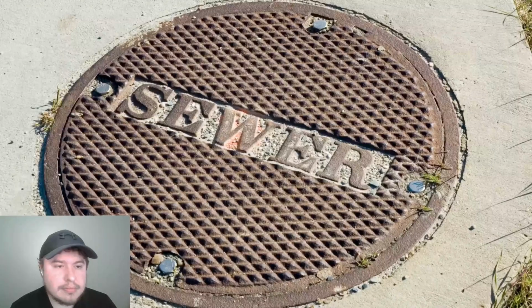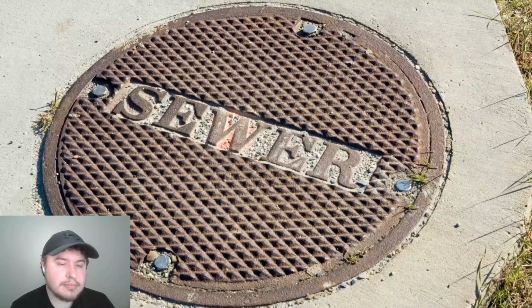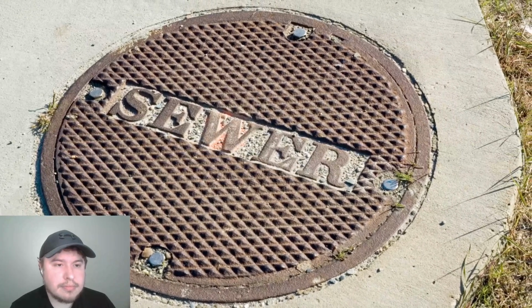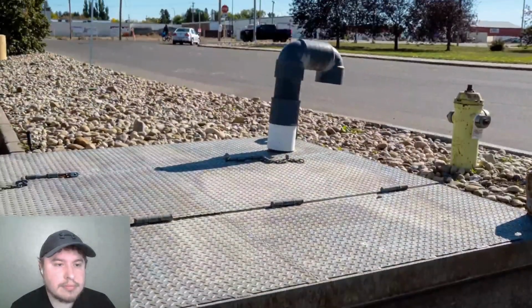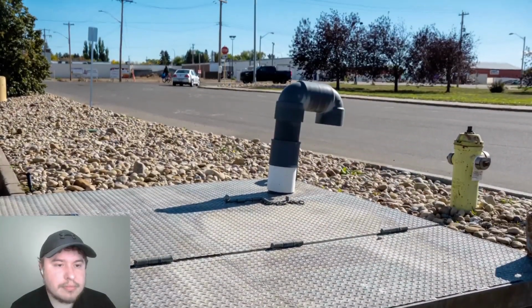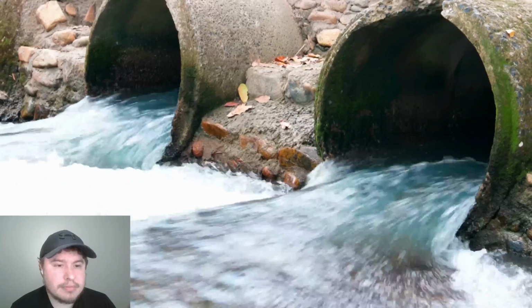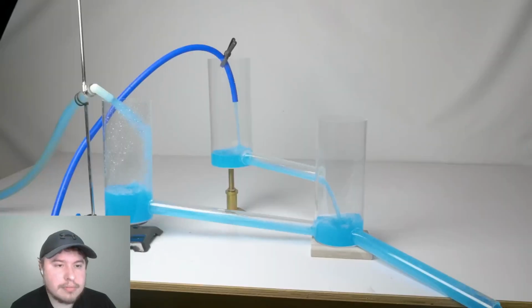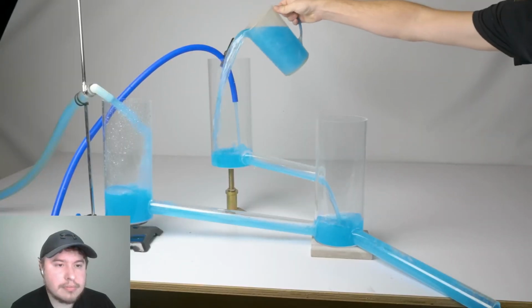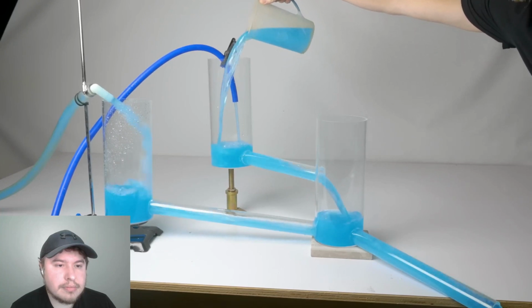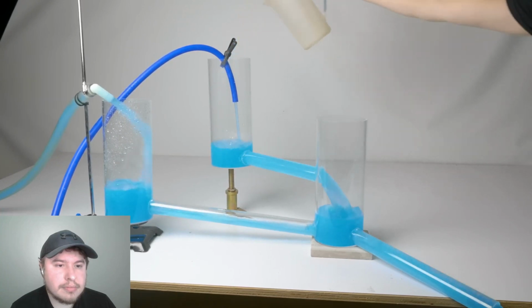In fact, a lot of places require sealed and bolted covers if the top of the manhole is below the floodplain. That's why you sometimes see these air vents sticking up out of the ground. Many older cities use combined systems where stormwater runs in the same pipes, so rainwater in sewers can be a major challenge. And you can see when you get a big surge of water, the manhole can store some of it, smoothing out the flow downstream.